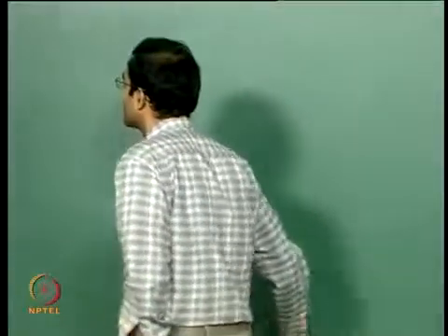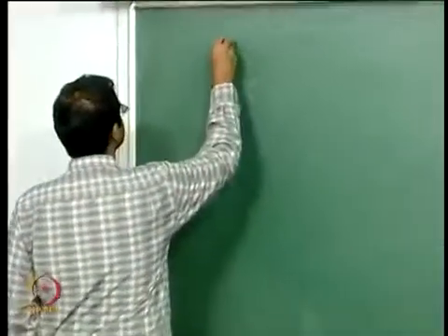One is casting that into the form of stream function vorticity equations, which we have derived, and if you apply that to a typical problem, which is an external boundary layer flow, we can use some scaling arguments, do some order of magnitude analysis, and then conclusively show that certain terms can be dropped, provided that you are dealing with sufficiently high Reynolds number flows. Under that approximation we have derived what are called the boundary layer equations. So let us summarize the boundary layer equations which we derived in the last class.